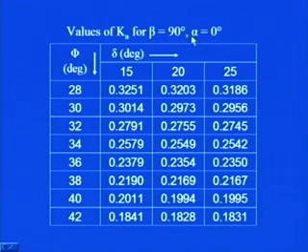that shows that the back face of the wall is making an angle of 90 degree from the horizontal, that is, the back face of the wall is vertical. So, if these two angles are fixed, that is, the backfill is horizontal and the back face of the wall is vertical, then for different values of angle of internal friction phi and different values of delta, corresponding values of Ka have been tabulated in this particular table.